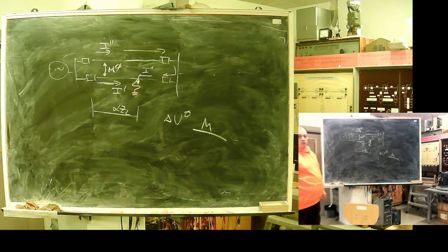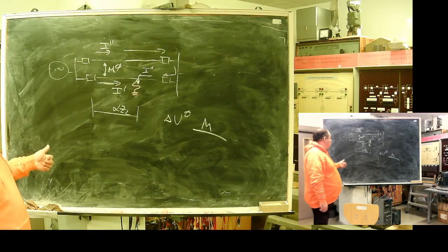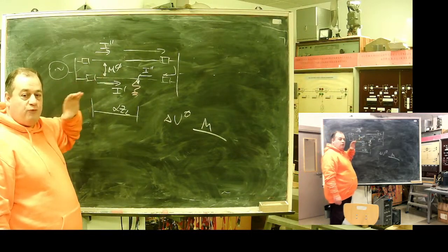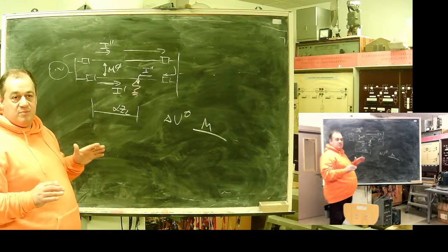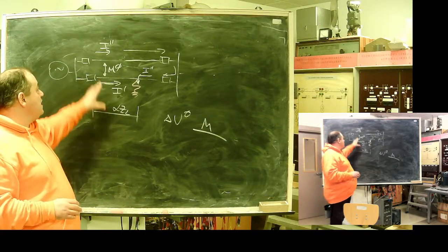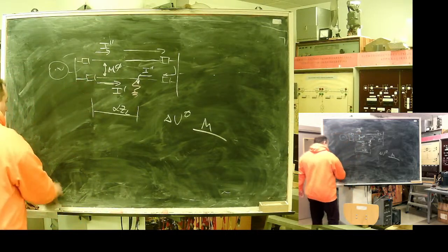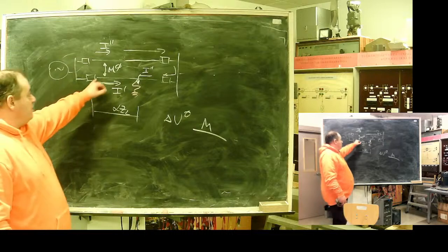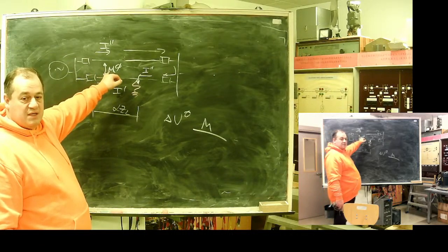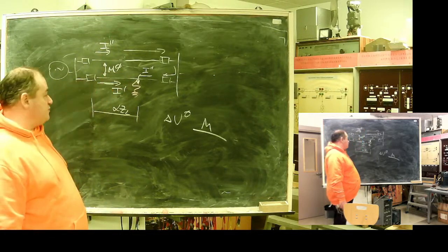So take time on modeling and perform a calculation for the regime, of course, for a parallel line. In the more severe case, you have two lines sharing the same tower system. In this case, it's mandatory. You need to check what happens. Here, the influence is in the non-trip direction. Resistance increases, so the observable fault point goes out of the zone.